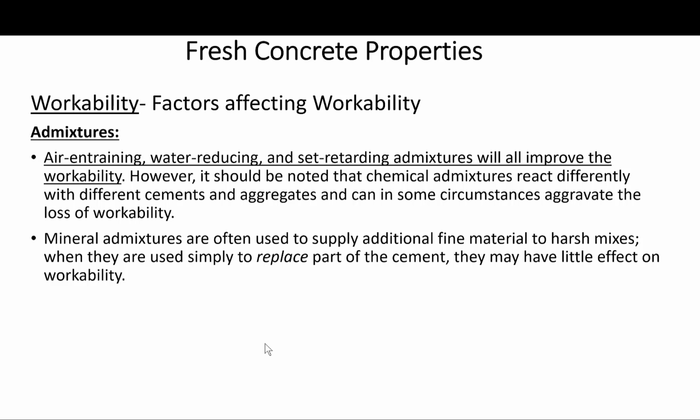And again, trial mixes on the same material you are using for that particular job. Since we cannot yet predict exactly how a given superplasticizer will react with a particular cement, this must be done empirically through laboratory and field tests, trial tests.